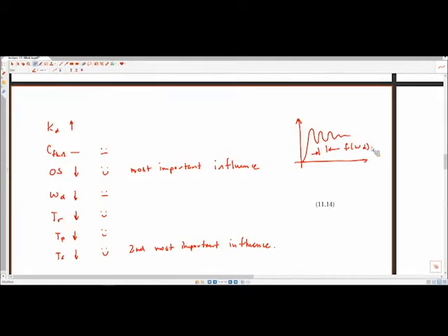But we have sensors on the system that are then sampled, and also all sensors are noisy. And these are pretty clean because they're encoders, really clean sensors. But there are some sensors like temperature measurements, etc., that are really noisy signals. And if you just apply a really strong derivative to that case without any filtering, it can be a really, I guess we'll say, bad thing.